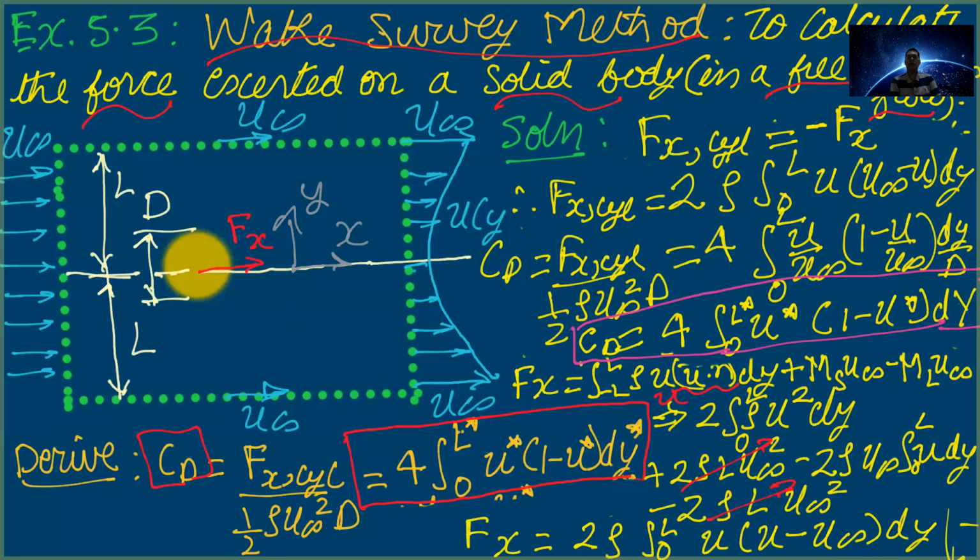So in this problem, as compared to the previous problem, note that intentionally the mass flow rate was not given on certain boundary, and the main learning, which is different from the previous problem, is you need to apply the mass conservation. Another difference is that in the previous problem, you were always given a single value velocity at the inlet and outlet, whereas here you are given a velocity profile. And that we had used here to calculate the x momentum flow rate.